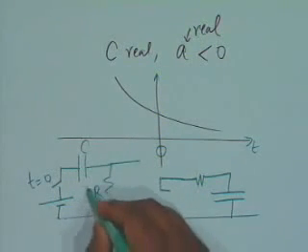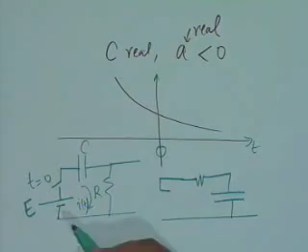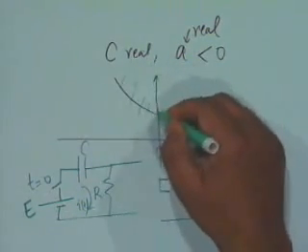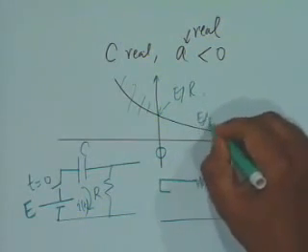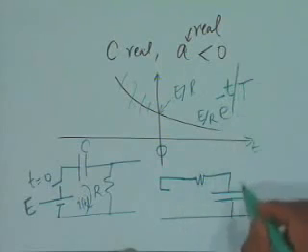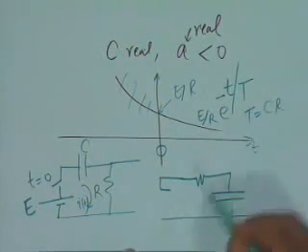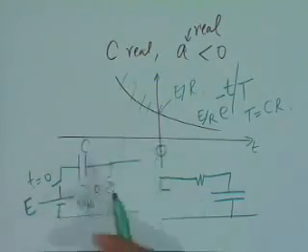And if you look at the current, what is the initial value of the current? The battery divided by the resistance, E by R, and then it decays exponentially according to E by R, e to the power minus t, small t, divided by cap T, where cap T is equal to CR. So the decay of current in an RC circuit excited by a battery is an exponential signal.